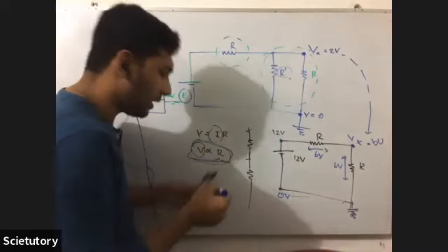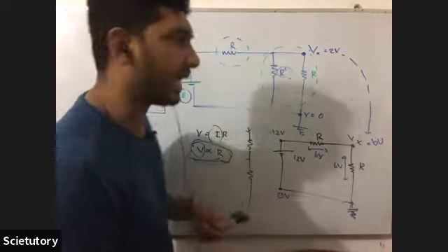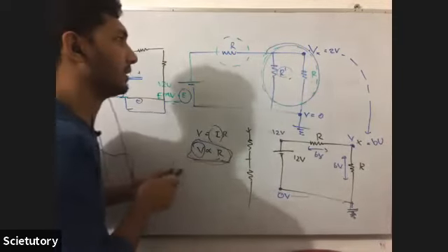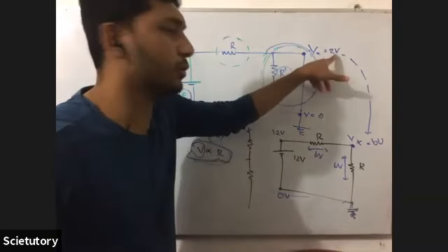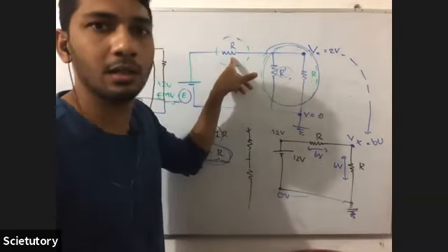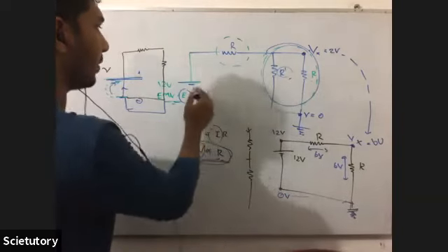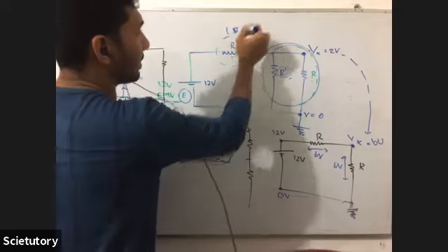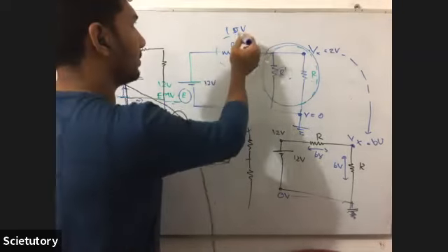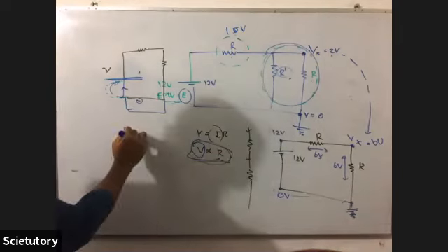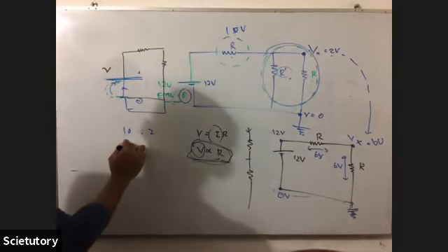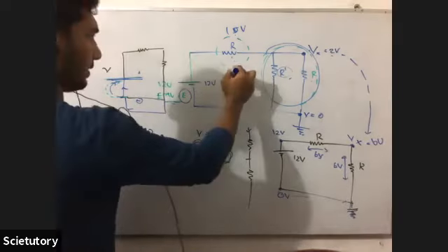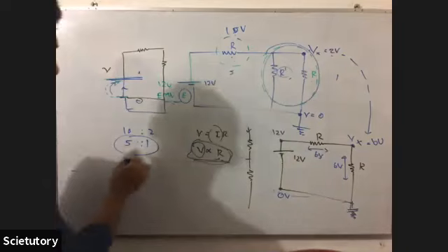Now, according to the voltage divider principle again, these parallelly connected resistors actually have a drop of 2 volt. So 2 is gone, it is 12. So the other part should have a drop of 10 volts. So what is the ratio? 10 volt is to 2 volt. 5:1. So for this one, it is 5. For this part of the circuit, it is 1.